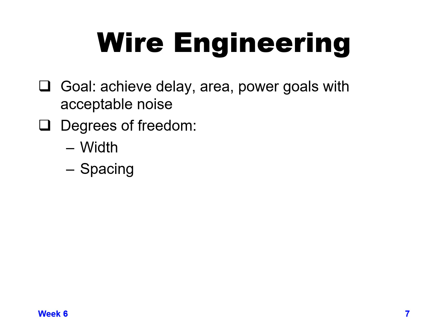Depending on how long your wire is and how big a driver you have on your wire and how much load you have at the end of your wire, all of those go into it. You might find that a narrower wire gives you less total delay than a wider wire in certain cases. So there's lots of factors to look at.